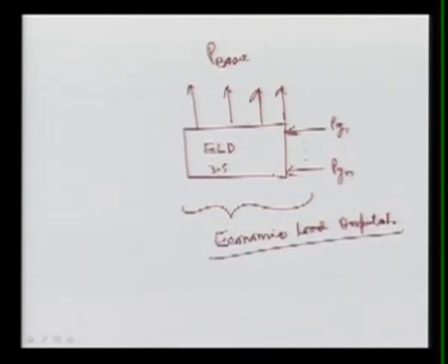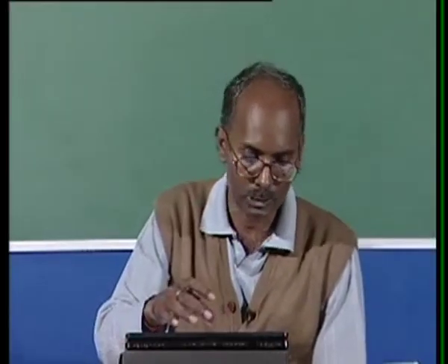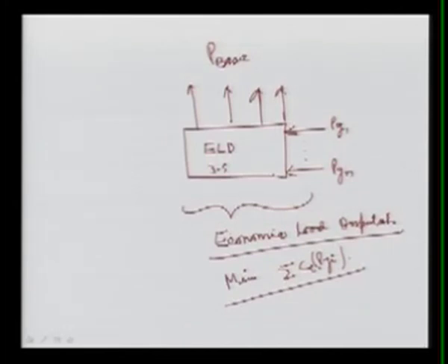Here our intention is to minimize the total cost of the system, the total cost of generation, basically we are talking here in economic dispatch. So it is a summation of the cost of generation of unit i. Here I can say that it is a function of real power output, and then we have to minimize it subject to the various constraints, that is the power balance equations. So this is your economic load dispatch logic.